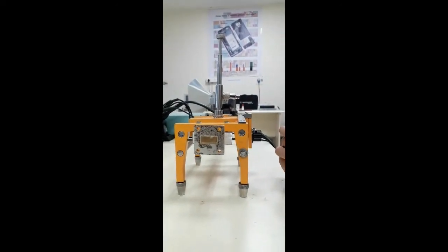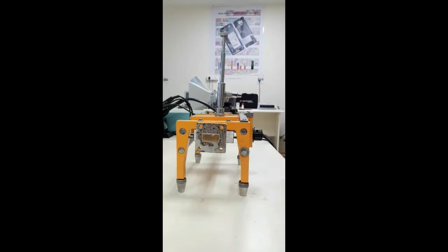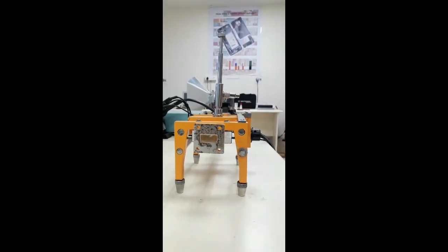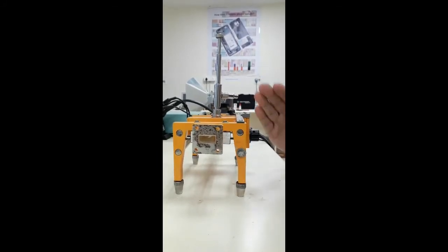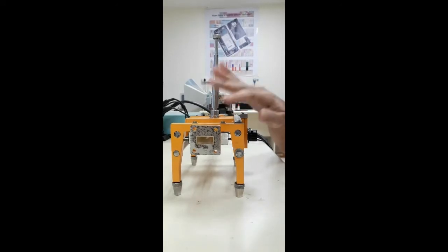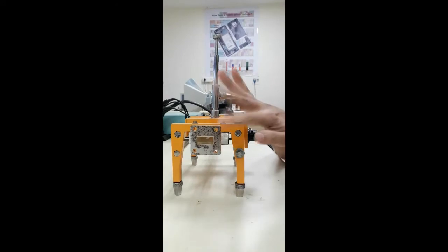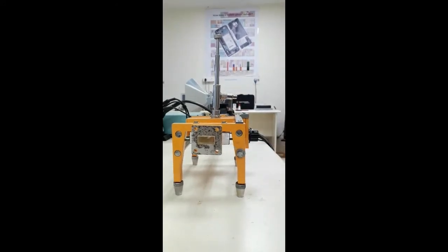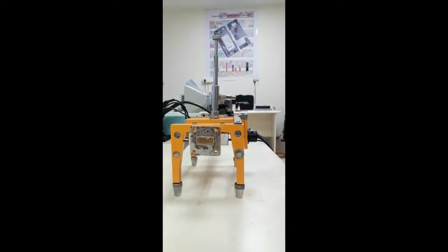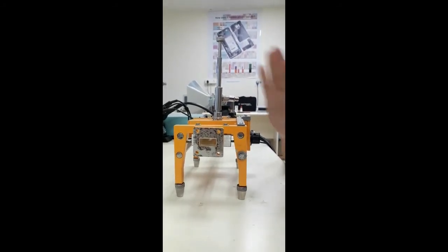So the dimensions of this waveguide are designed in such a way that the dominant mode of this rectangular waveguide, which is the TE10 mode, is able to propagate with a cutoff frequency that is in the range of about 6.5 gigahertz. So any wave which wants to travel in the TE10 mode must be given into this waveguide with a frequency above the cutoff frequency, which in this case is roughly 6.5 gigahertz. You can calculate the exact one yourself.